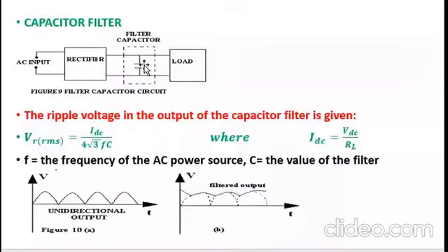So what happens is this: whenever the signal is rising from 0 to maximum, the capacitor will be storing charge. When it is trying to fall from maximum to 0, the capacitor will start releasing the stored energy, and for this reason it will not allow it to go to 0 because it is producing output to counter that.